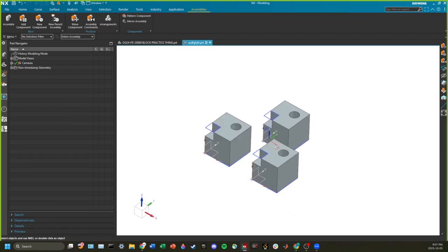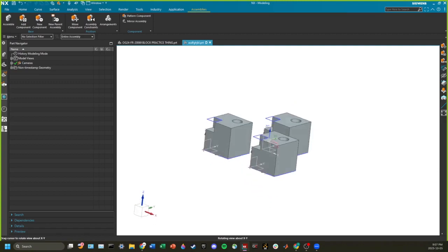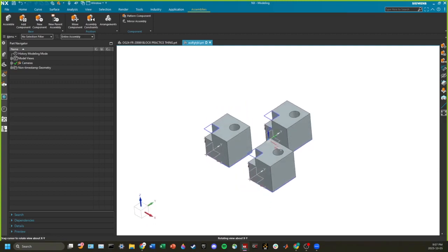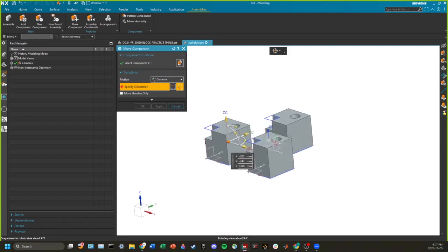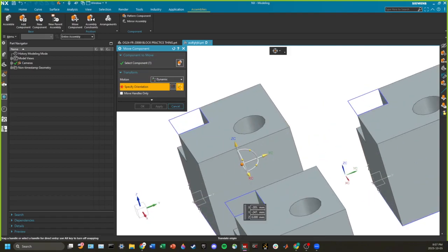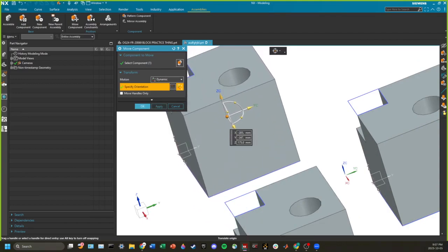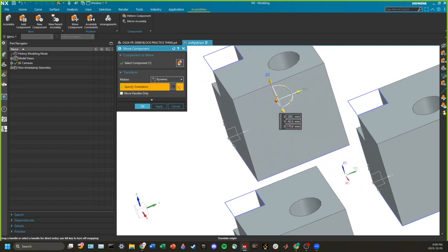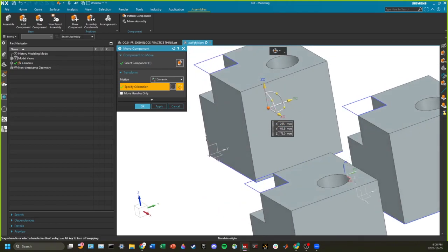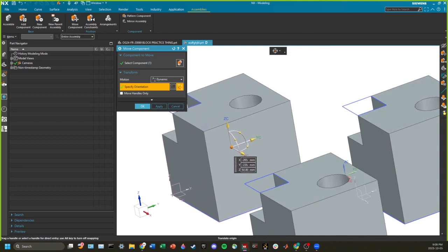I want to assemble them. They're just kind of sat on a table right now, if you want to think of it that way. So what I can do is move them. If I click one of them, Specify Orientation, this handy thing shows up. It allows me to drag it in any direction. As well, if I grab this dot, I can freely move it.